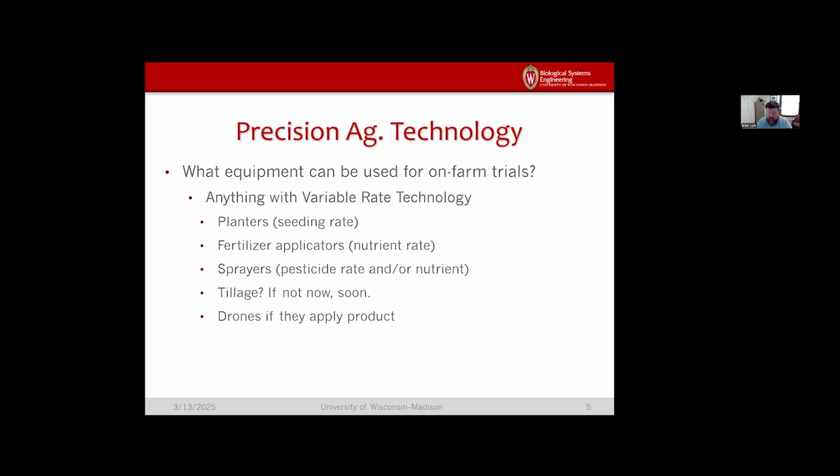One of the things you have to consider though is that spinner spreaders usually spread in sort of a bell curve. So the very outside of the spread width is a minimal amount of application, with the most in the center. What we do is overlap to match the centers and put out a certain application rate. So paying attention to how you're applying is a whole other thing to think about. Whereas if you have variable rates going down the field and you're spreading center to center, you may have to spread too wide to make sure that the center rate is what you think it is.